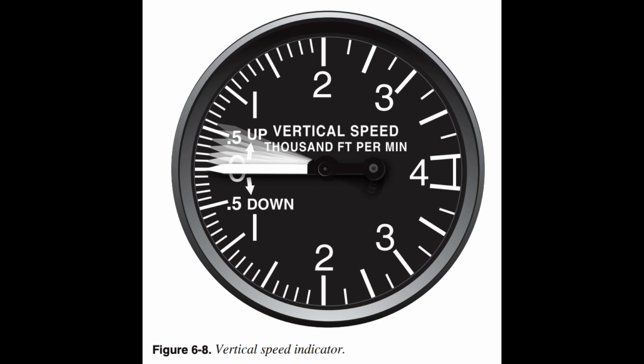Some aircraft are equipped with an instantaneous vertical speed indicator, IVSI. The letters IVSI appear on the face of the indicator. This instrument assists in interpretation by instantaneously indicating the rate of climb or descent at a given moment with little or no lag as displayed in the VSI.